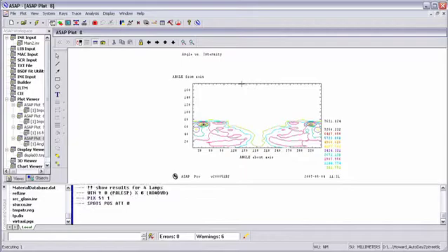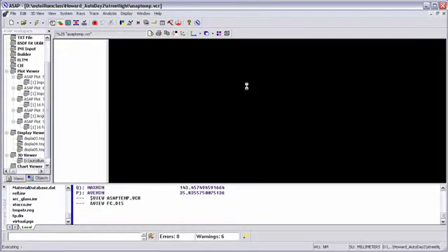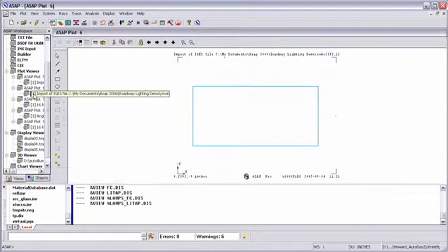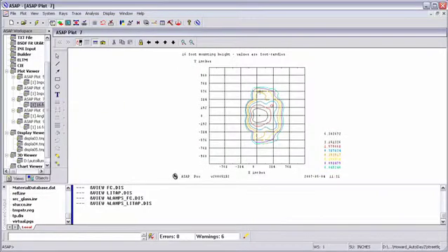Okay, you're going to see several plots come up on the screen, and we'll go back to each one of the plots and explain them. Okay, so the first plot is actually an illuminance plot of the individual lamp on the ground, and it's expressed in foot candles, and we've shown the contour. So the ground is labeled here in inches divided into grids, and you can see the output of the lamp in that format.